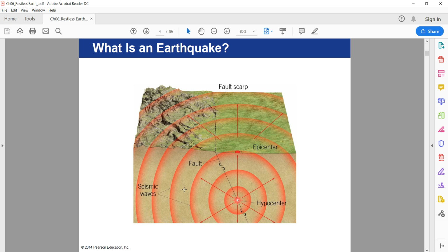So seismic waves are the energy waves that are released when the slip occurs. As I said earlier, this energy will be stored due to non-slip, as the friction does not allow the plate to slip. The elastic energy will be stored, and that will be released in the form of seismic waves whenever the slip occurs. So this is again the same schematic of two rock masses, and this is your fracture or fault line where the slip will occur.